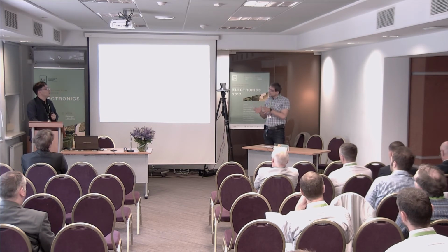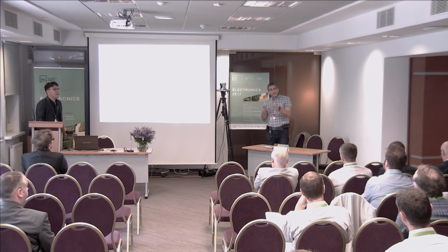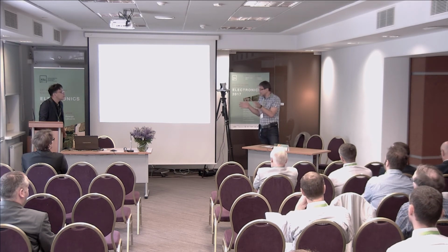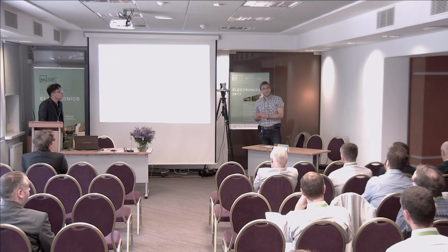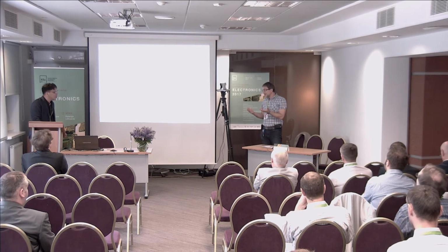So the question that Jan gave you is this: remember, Jan, Kim told that the essential reason why they discarded the DFT was that it is not giving the resolution. Actually, it may be that it is giving the resolution, because if you are able to estimate two different frequencies, you have the resolution. But more or less, they consider it as not giving the resolution, and then they go into super resolution algorithms, because the bandwidth that you are using, 200 megahertz, is less than you would like for the resolution.